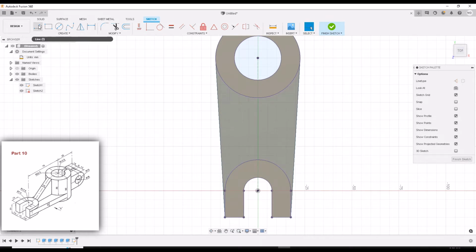All right, now we want to create that center section. Let's do a construction line. Okay, so the construction line is going to go through the center of the part. You want to start here at the center point of the ID/OD, kind of drag it up, click it. Now you see that little icon that popped up? That's for the midpoint. That's exactly what we want. So when we left click it at that intersection and drag it up, it should connect to the next midpoint, and that's what we want. All right, now let's turn off the construction line, go back to the solid line.